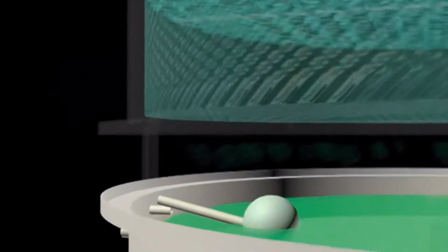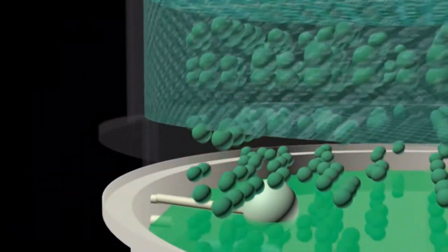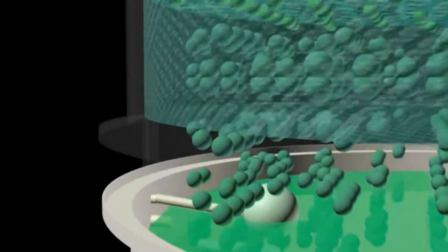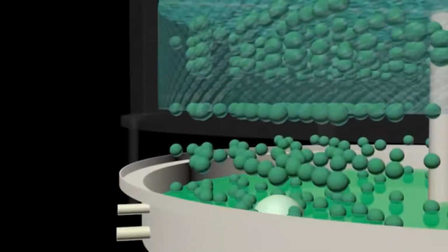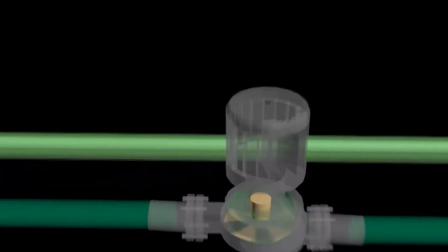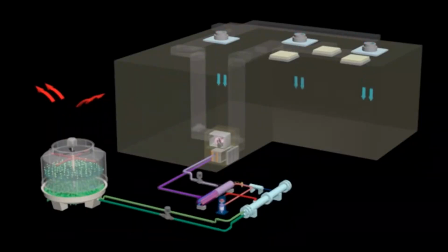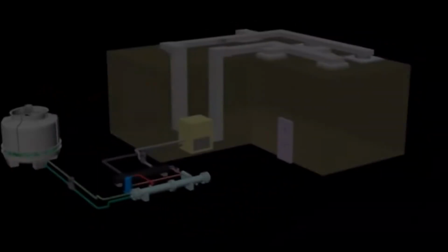The buoy system at the water basin is connected to the make-up water tank. It works for adding water when the water level in the basin decreases to a certain level due to evaporation. This condenser water cycle will continuously flow as long as the centrifugal pump is in good working condition. This explanation hopefully will enhance the student comprehension regarding the system. The centralized air conditioning is the commonly used system and it's very important for the student to know the system well.